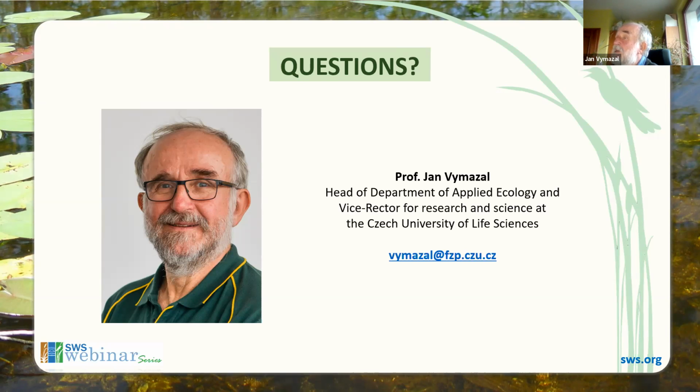For example, if we had floating islands, these floating treatment wetlands, then we can very easily harvest the roots and rhizomes. I don't want to say below ground because it's floating in the water, but you can harvest also the roots and rhizomes, and then you would probably increase very much the removal through harvesting. But then you should either leave some plants in place or you should replant if you remove also the roots and rhizomes.